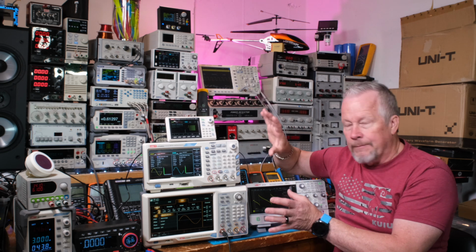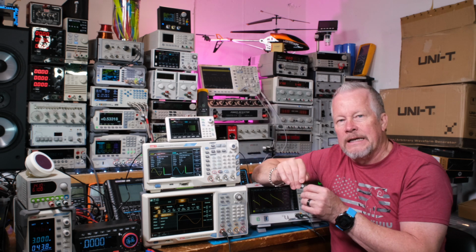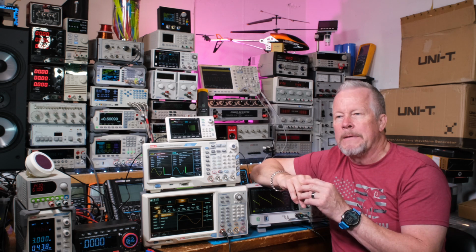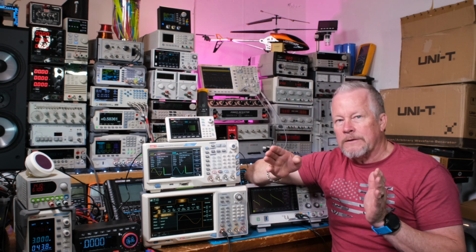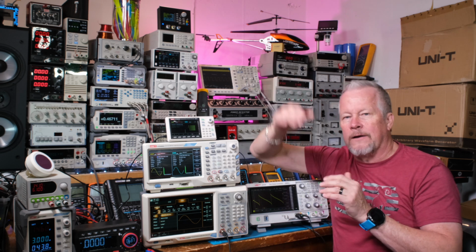Now, the other thing about all these generators: as the frequency goes up, the voltage drops down, okay? You can imagine the slew rate, how fast you can climb, how many volts per microsecond. If you have to go a lot of volts, then it takes more time to climb, so your frequency goes down. That's just the way it works, right? You have to have super fast rise times to be able to go real fast at higher voltages.